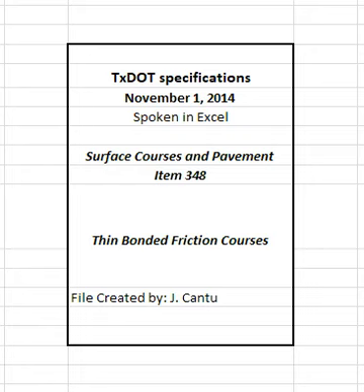Maintain the inline measuring device, when AR binder is specified, to verify the AR binder viscosity between 2500 and 4000 centipoise at 350 degrees Fahrenheit unless otherwise approved. Record AR binder viscosity at least once per hour and provide a daily summary unless otherwise directed.